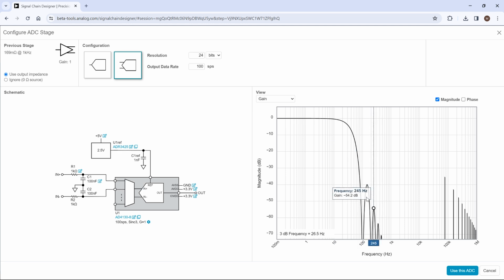This is a sigma delta ADC. We can see it already has internal filtering here. So we can see that this is from the internal filtering. And then generally, nearly every ADC has some sort of anti-aliasing filter to cut down the noise in front. So we put the recommended filter from the datasheet there for you, and we put the recommended reference for you. You can, of course, go change those things if you wanted.